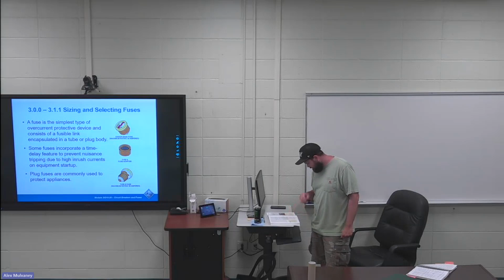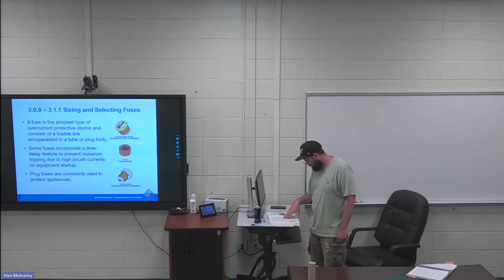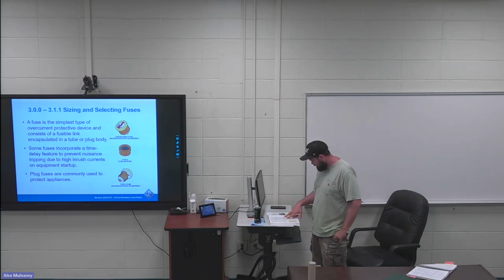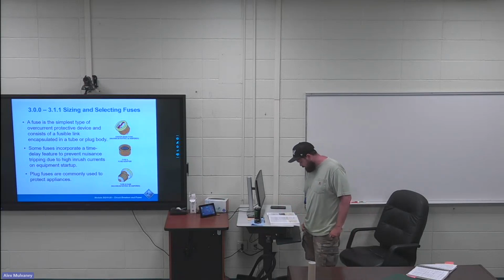Next paragraph, again about the second half of that paragraph is highlighted, right after where you see the 0 to 30 amps in the middle of the paragraph. Each type S fuse has a base of a different size and matching adapter. Once an adapter is screwed into a standard Edison-based fuse holder, it locks in place and is not readily removed without destroying the fuse holder. As a result, only type S fuses with a size the same as that of the adapter may be inserted.